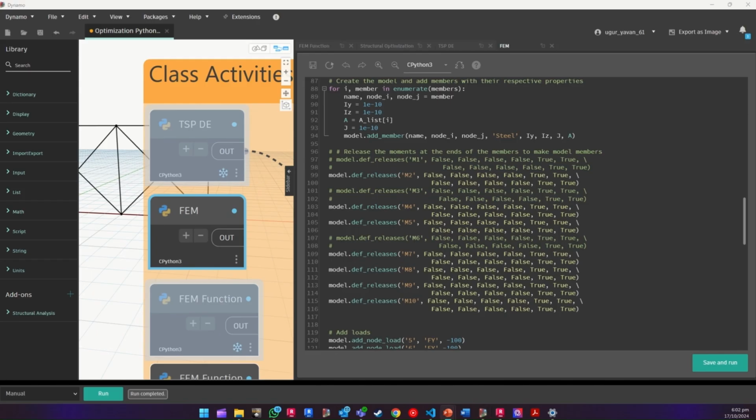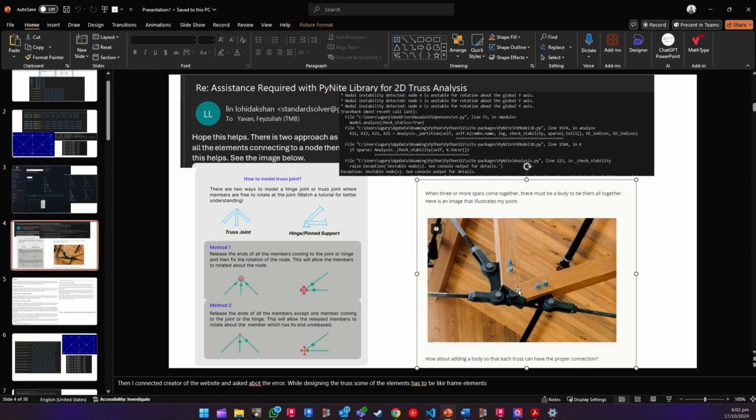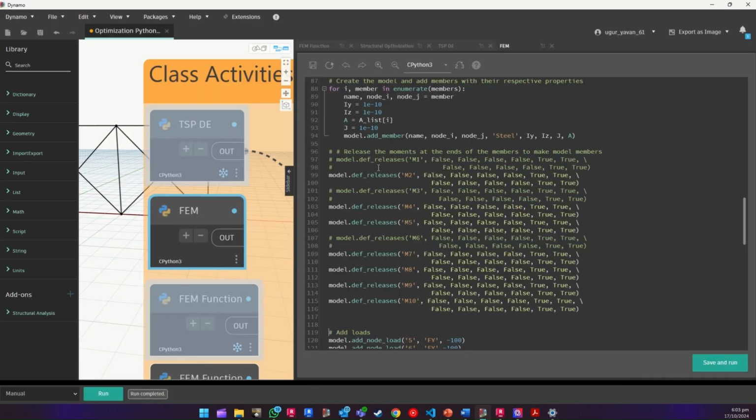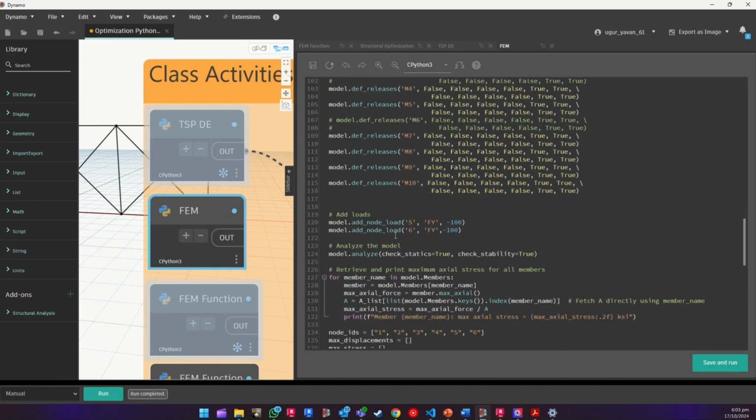Yes, here. So here, as you can see, in real-world engineering problems, you always have some stable part that holds the elements together. Then you are adding the pinned connections. Okay, so that's why you have one element to actually connect these two pinned elements. That's why here I'm not releasing all the elements, but I am leaving some elements to actually keep the structure together.